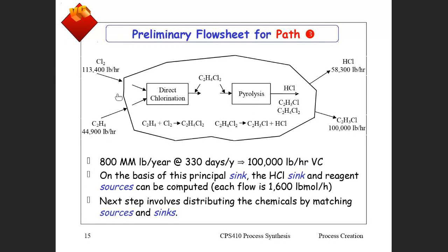You would always be putting in a stoichiometric amount, because if you put in excess ethylene, that ethylene would have to come out at the back of the reactor, and it is a valuable raw material that you're using. So always stoichiometric amounts coming in, stoichiometric amounts coming out, unless there is reason that you don't have that.